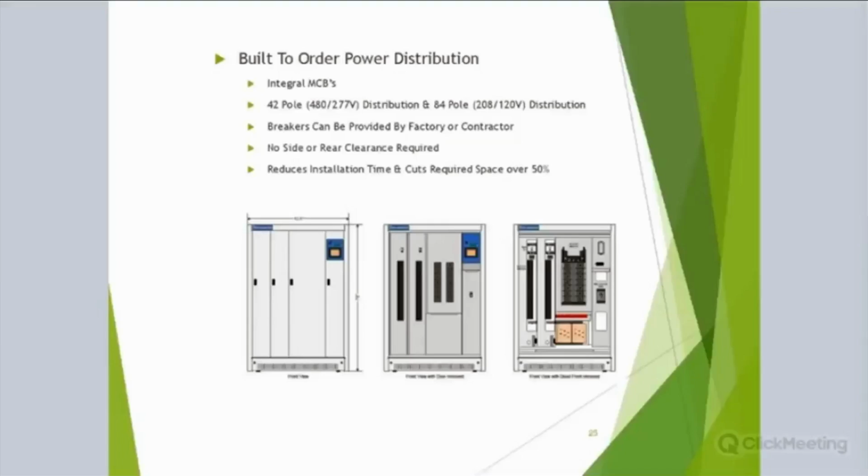I can provide an energy station that is like a PDU, but it includes the 277, 480 volt panel built into it, which then feeds the transformer, which then feeds your 120, 208 volt panel. All of which is, again, in one box, less installation cost, much lower footprint, and all of these products can utilize ultra high efficient transformers. So you get the best of all worlds moving forward.